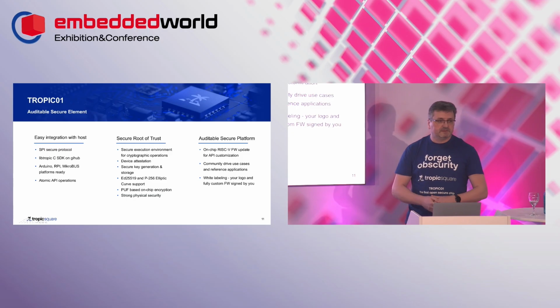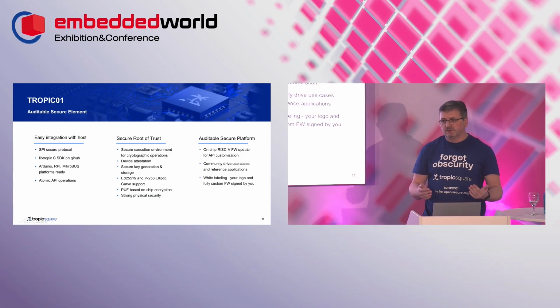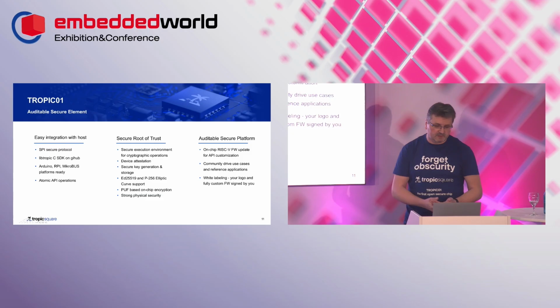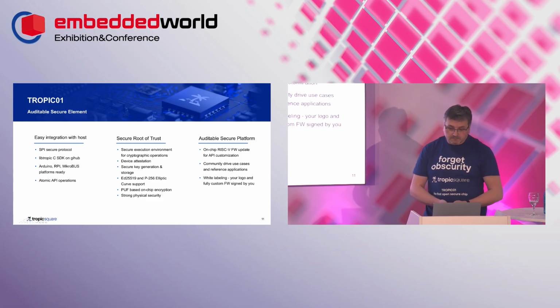Currently, the chip is designed with atomic API operations, so we really focus on simple use, and you can just pick up the functionality which you need. If you design your application and find that some features might need to be chained slightly differently, or you want to combine multiple commands together, it can be done by firmware updates on the silicon.